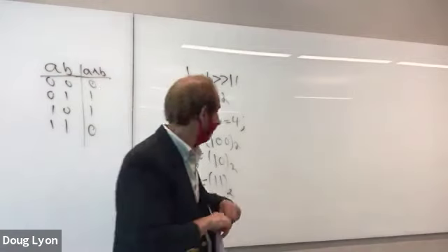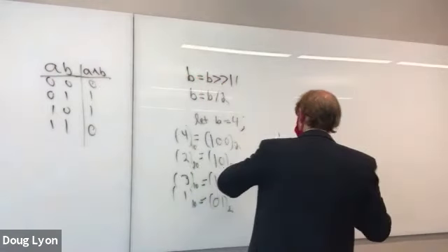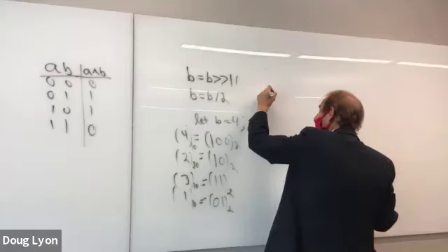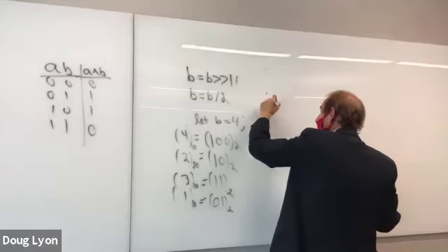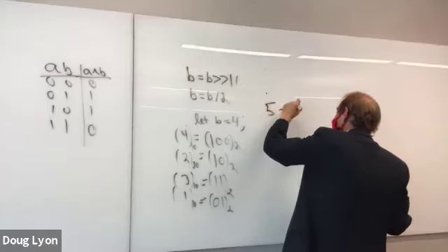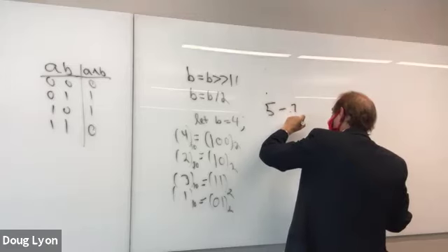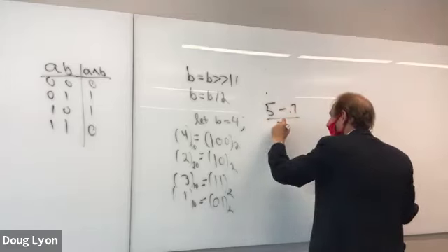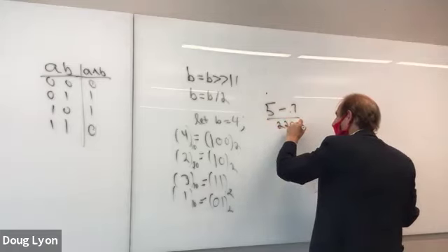Yeah, so it's supposed to be 4.3. It should be. Oh, there's a bug. Okay, so there's a bug. But if you've already done it, I can't really correct it. So anyway, it's 5 minus the voltage drop, which is probably 4.3, divided by 220 ohms.